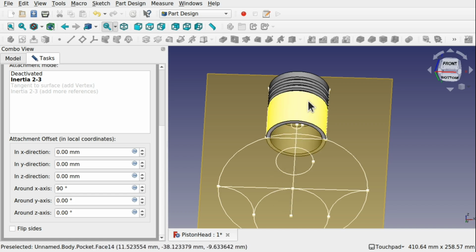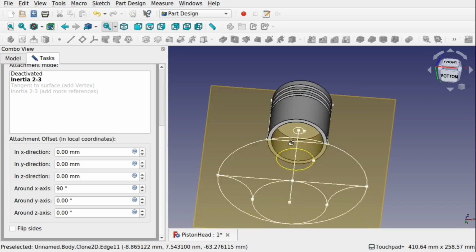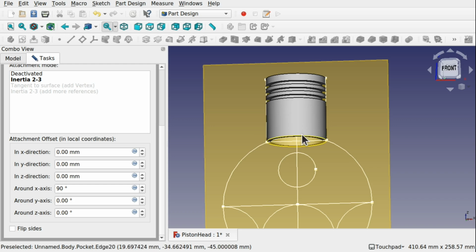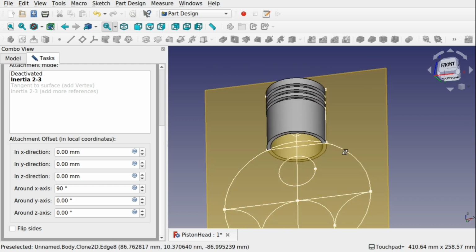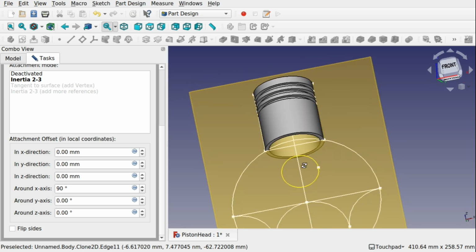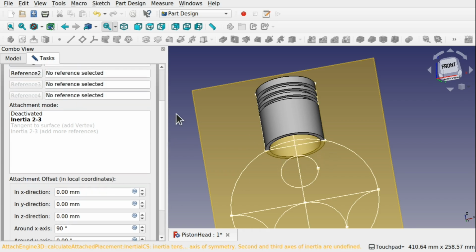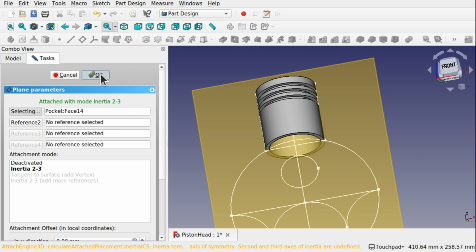Now where does this connection rod need to sit? So it's going to be flat going in here, so the hole to the connection rod is there, so that is correct. So that's going to be sitting there. So our curve comes in here with the crankshaft, like so. So that curve will be removed from the bottom there. That's good. So I've worked out that's correct. We may need to use the flip side to flip the sketch around the right place, but that should be fine because we can put a sketch in either side of this. It's in the middle anyway, so that's okay.